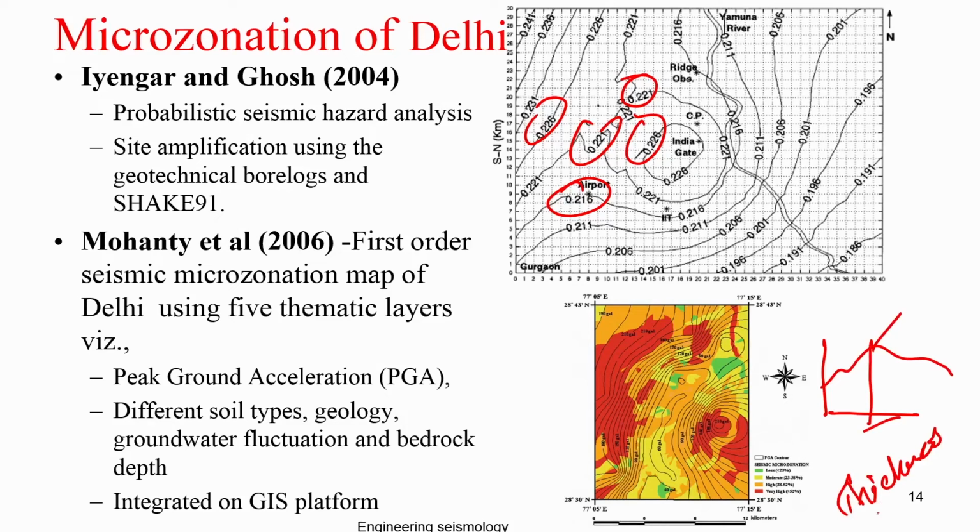That thickness again depends upon the regional correlation established between the H/V ratio and predominant frequency. As we have seen, the geology and isoseismal maps match very well, and similarly the thickness and failure pattern isoseismal maps matched very well in past earthquakes. So knowing the thickness will help you know where the more severe earthquake hazard can be expected for the same earthquake.